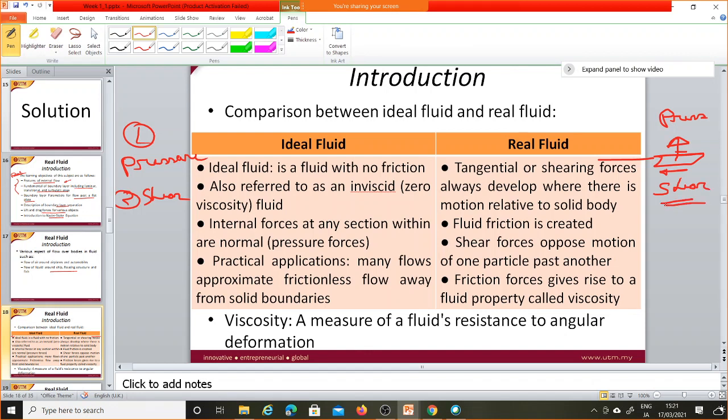This shear force is actually the friction, so you have to overcome it. In the case of a ship, when we have the resistance, it has several components that I will talk about again later. It has the frictional resistance and the wave making resistance. So mainly it is two basic parts. The frictional resistance actually comes from the shear force.